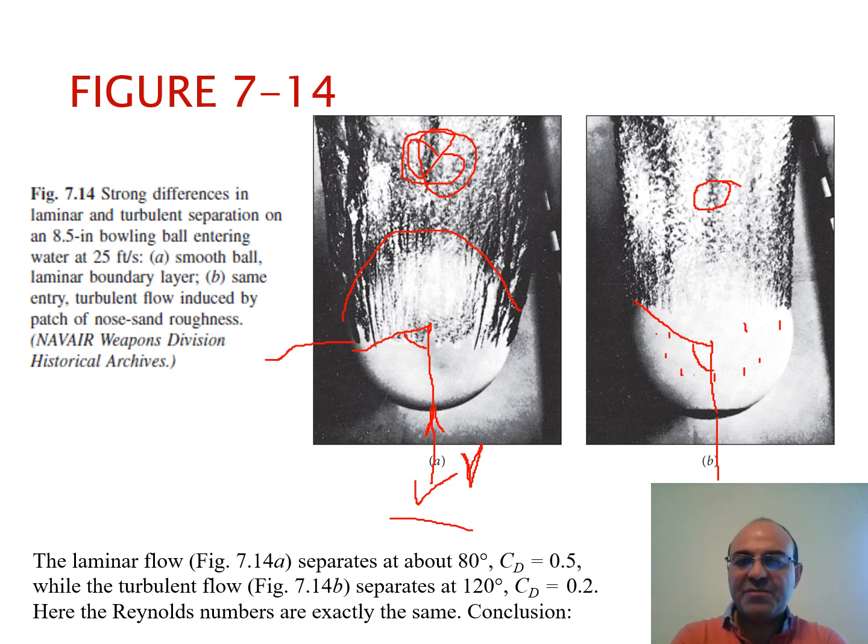which is turbulent. So as a result, we could see that in case B, the ball will attain a larger speed, or it will move faster. It really depends on other things as well, whether it's going to accelerate or decelerate, but there will be less drag force in front of the ball in case B, where it's turbulent.